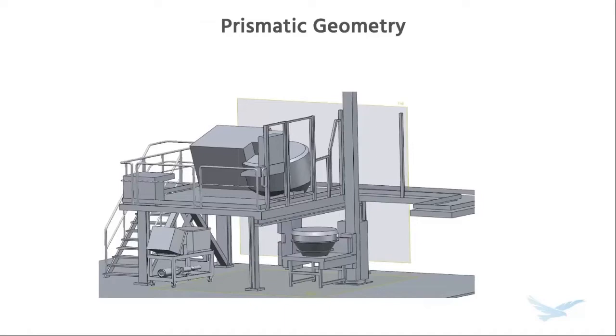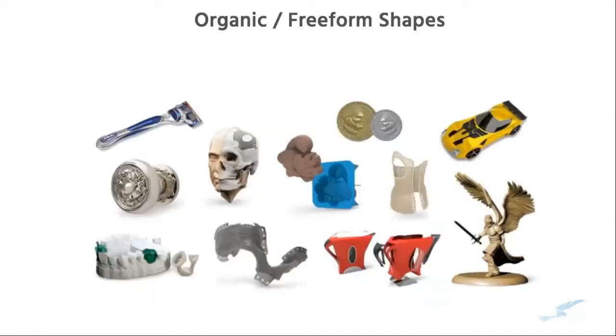So this is the dominant method for a reason. It's relatively efficient, maybe not in terms of material use because we're cutting all this stuff away, but again, those shapes like the bracket are easy to describe, easy to design, easy to create with rotating cutting tools. And so it's dominant for a reason. It's still the best current fit for most of what we do, at least for now.